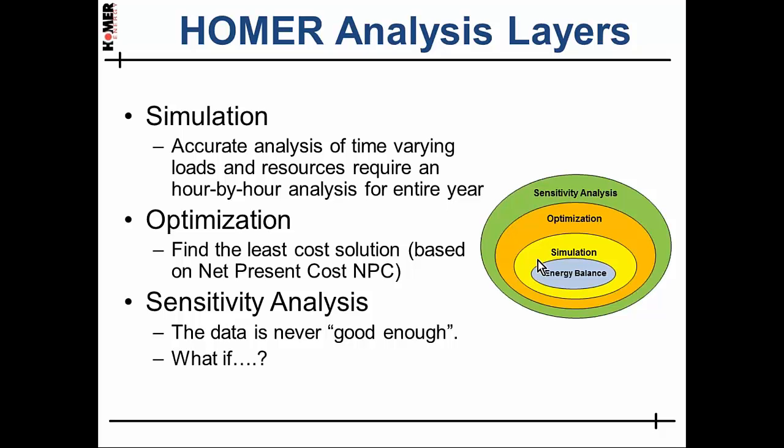You could imagine simulating many different systems with different amounts of solar photovoltaics, for example. The optimization layer would simulate all of these different systems, and allow you to compare them. Now, by trying a lot of different system designs, you can find the design with the lowest cost. Now, we've recently enhanced optimization in HOMER Pro with our optimizer, and that helps HOMER Pro to find the low-cost system by automatically sizing PV, battery, wind turbines, and system converter for you.